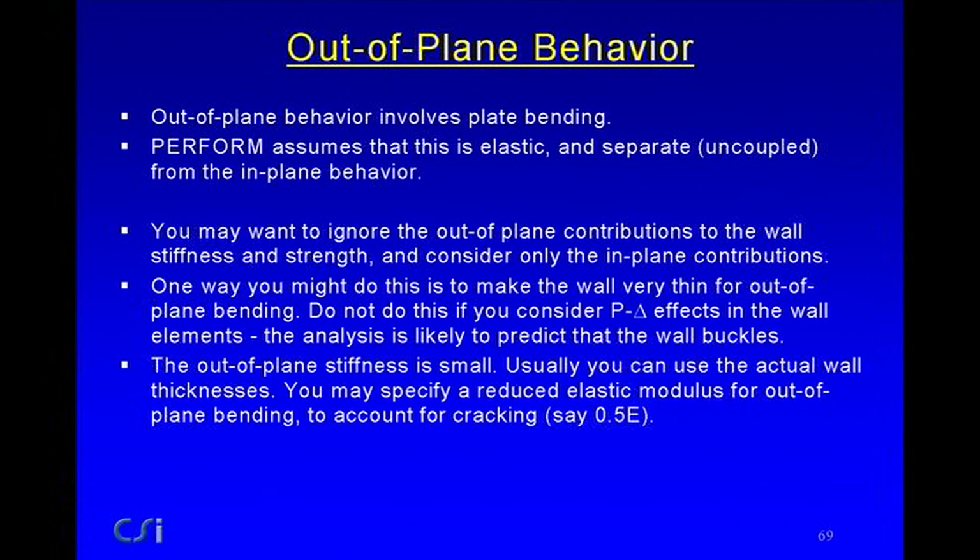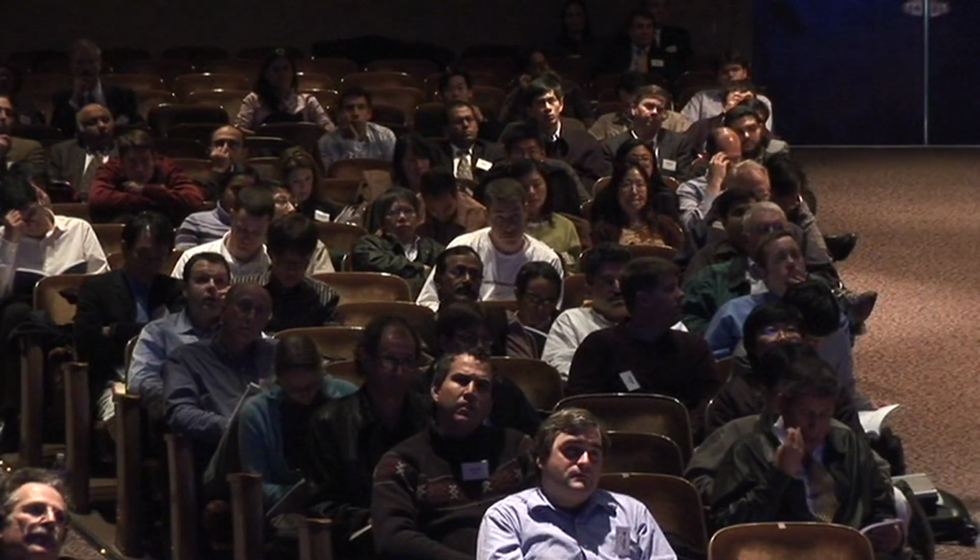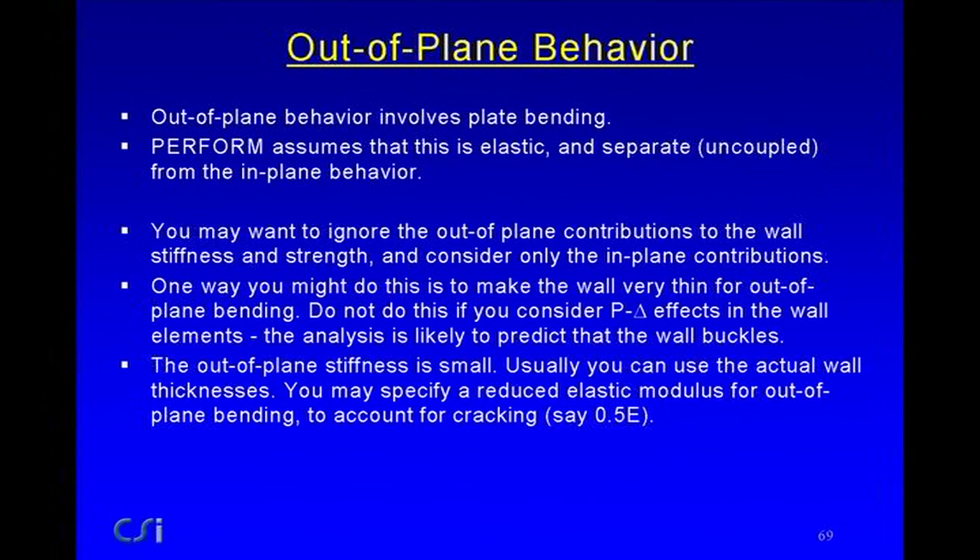Out-of-plane behavior. Now, out-of-plane behavior is plate bending. And Perform assumes that this is elastic, and so it will not do a cracked slab analysis. We do have another program, Perform Collapse, which does have a cracked slab analysis, but this is not available in Perform 3D. So out-of-plane bending is elastic, and it's also separate or uncoupled from the in-plane behavior. And let's not worry about the rest of this. It's kind of a detail.